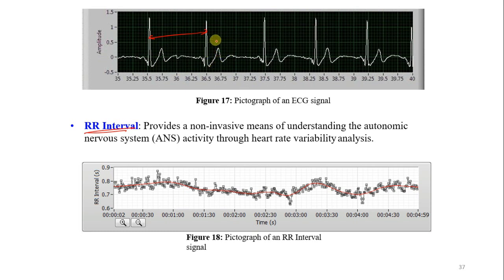Okay, or heart rate variability signal. So once we get this heart rate variability signal, then we apply an averaging filter to get the average envelope of the signal. So you get this red line, which is the average of the other intervals what you have got. And now this signal is used as an analysis tool for further prediction.